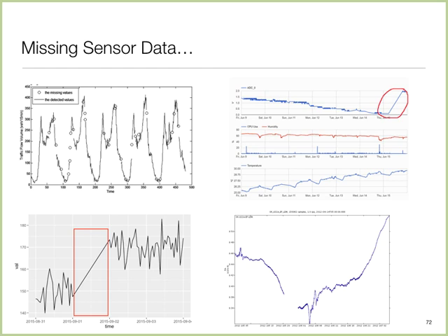So you have to be prepared. Sometimes it's software, some network outage, just something. Maybe Android decided to kill your sensing app because it was consuming too many resources, or any number of things can happen. So it's not just calibration, but these kinds of issues. Sometimes outages have other implications: if there is a network outage, your sensor may still be collecting the data, but the timestamp on that data may become off because it's not able to time sync back. So again, you need some way of handling that. Rainwater falling on the camera of your car is another example.